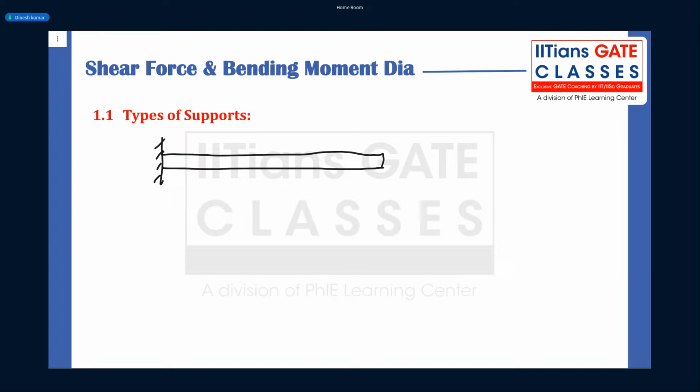Why can't it be inclined, horizontal? It's not necessary, Mr. Arkazit, it has to be vertical. Any slender structure, if it is undergoing compressive load, and the structure is what? A very long, prismatic, slender structure undergoing compressive axial load may fail in buckling. And if a structure fails in buckling, it is what?